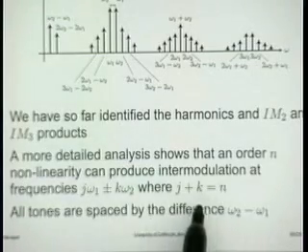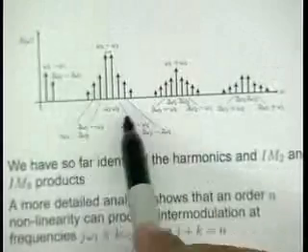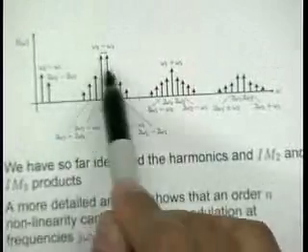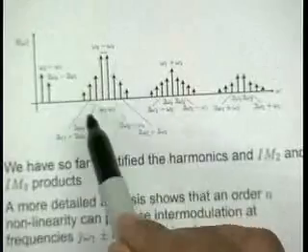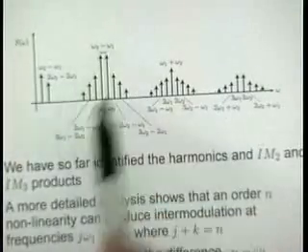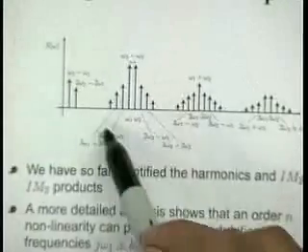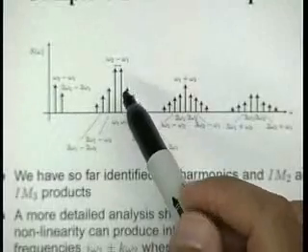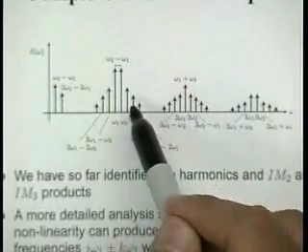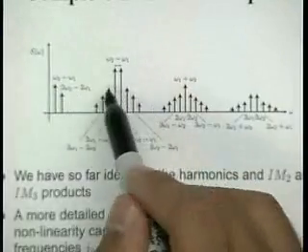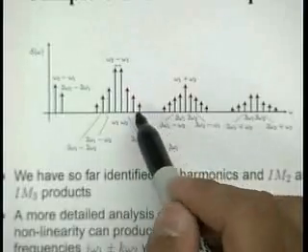So in general, all odd order powers generate distortion products which basically go right next door to your fundamental signal. So if you're worried about in-band distortion, you really worry about odd order distortion. In particular, the strongest term is your IM3 term. And then next you have your IM5 term, and then you have your IM7, and so on and so forth. Okay?